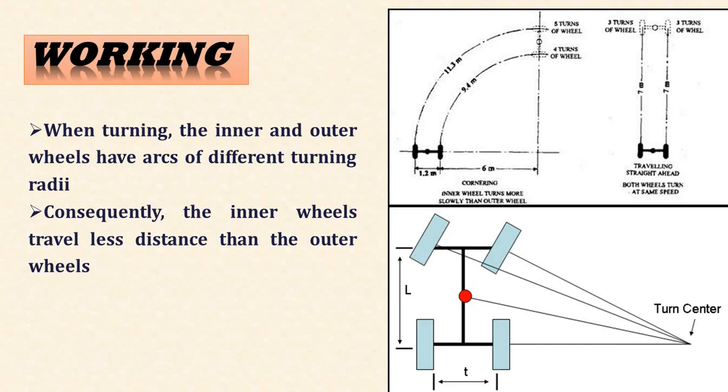The planet pinions are still turning and rotating on the cage shaft. Apparently, they walk around the slowed left axle and provide a greater portion of the power to the right side gear. The right wheel will then turn faster than the left wheel. The speed lost by the left wheel is added to that of the right wheel.